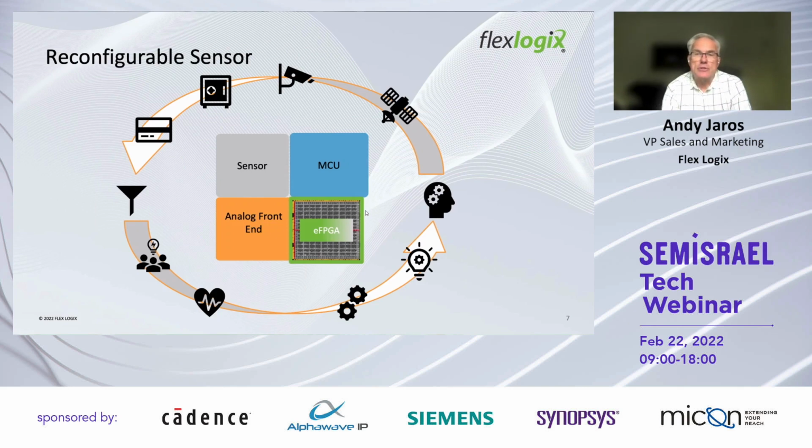Related to filtering our sensors, it seems like more and more devices these days are adding more and more sensors and generating more and more data. Filtering out the unneeded data is being pushed to the edge to lower the processing load on the main processor and lower overall system power. Edge processing choices tend to be small embedded CPUs or state machines. A small simple state machine can be programmed into the embedded FPGA to target a sensor for a specific application. Yet the sensor can be programmed with a different state machine for entirely different applications and not conceived of when the sensor was developed, thereby extending the market for that sensor.